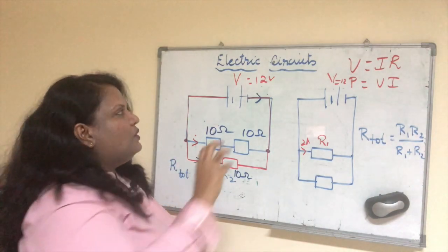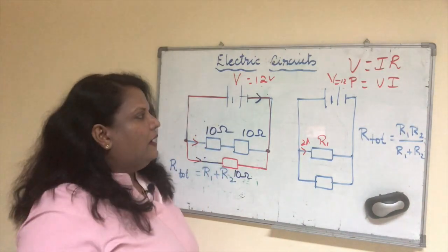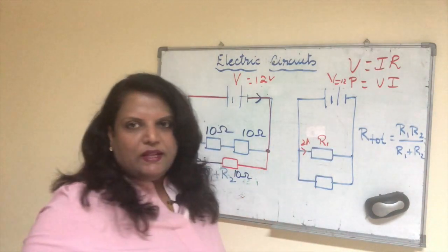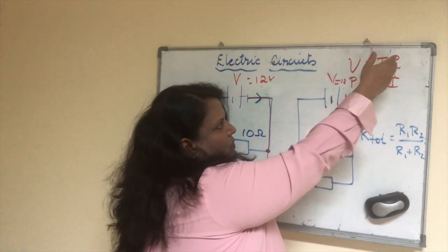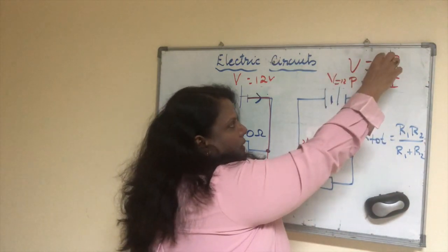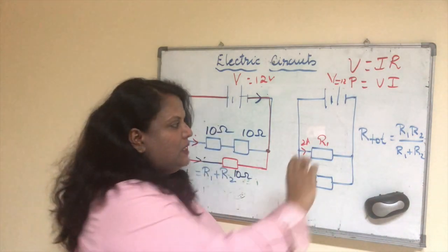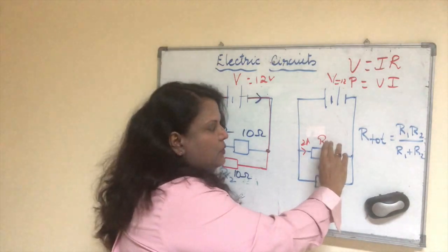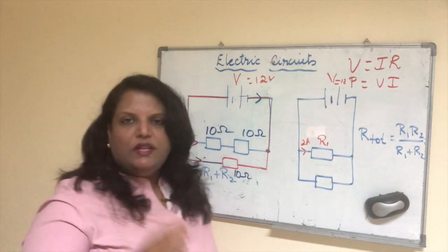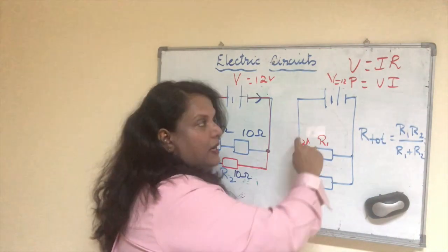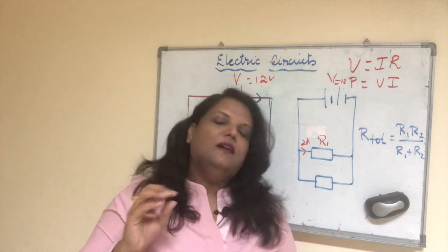So you've got the total voltage and the total current. If you're coming to a parallel circuit, it's very similar. You get the total resistance, and substitute in that V is equal to IR formula using 12. You will get that current I which flows up till this junction. If you want to calculate the individual currents, V over R1 and V over R2 will give you that current. These two should add up to the current that you have calculated earlier. I hope it's somewhat clear.